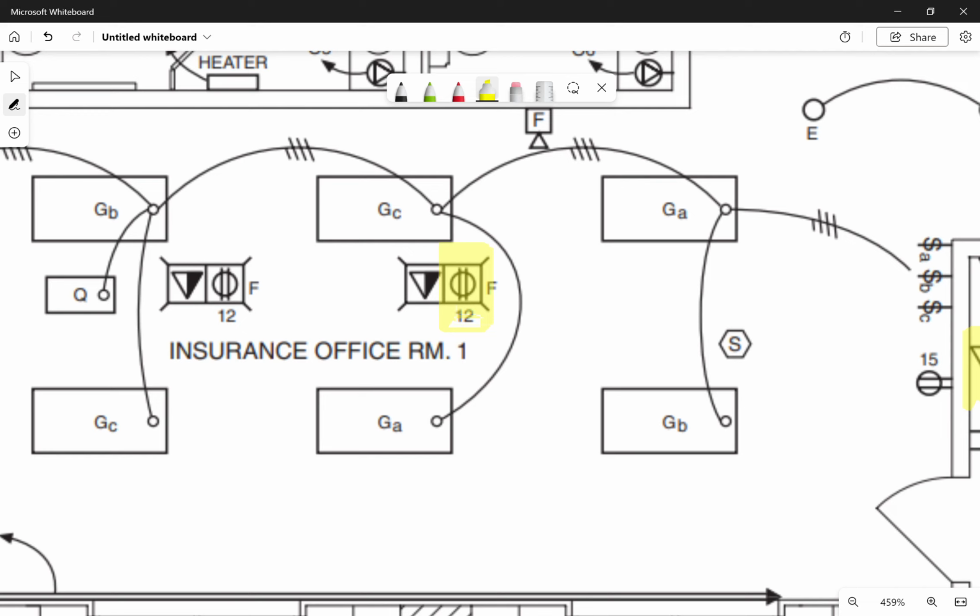It being inside the box, along with that little F to the side, is telling me that this is a floor receptacle, along with Ethernet or phone. Somewhere in the plans, there's a desk planned in this location, and rather than run an extension cord along the ground to a wall where we can power it, we're going to power it directly from a receptacle in the floor.